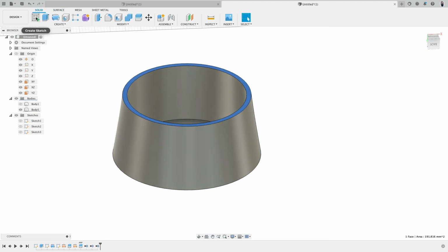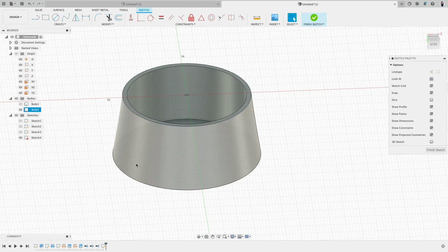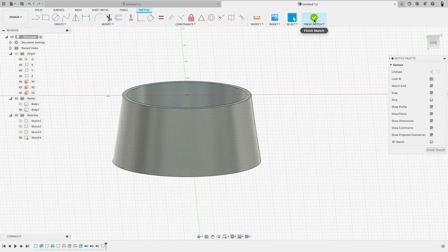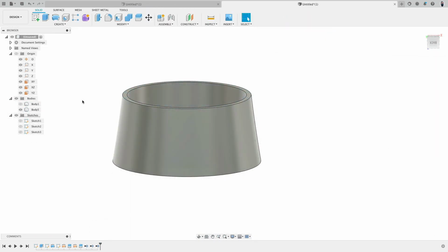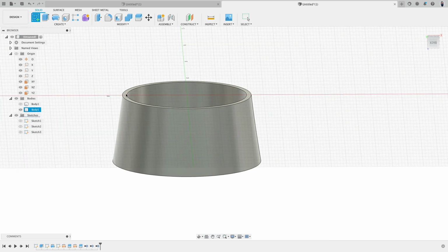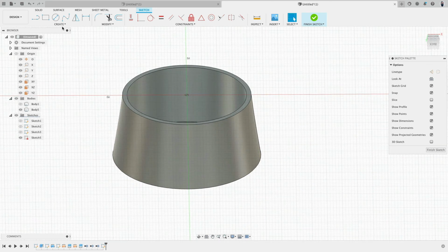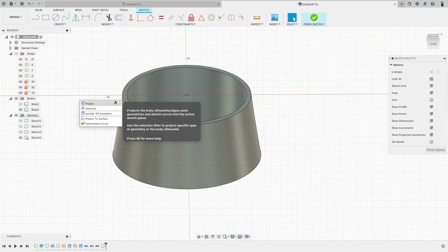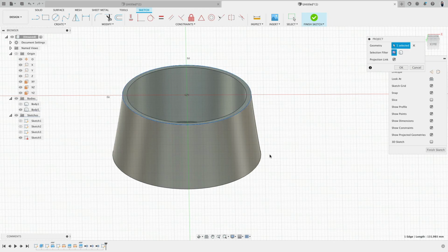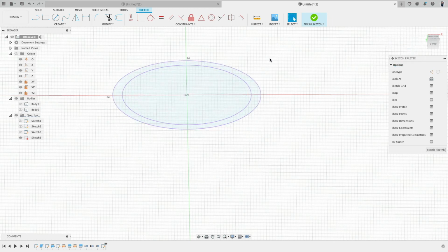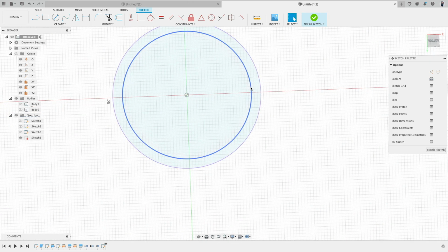Okay, solid mode, sketch right on this face I had selected. Or let me undo and delete this feature. Sketch. You see how I can select this planar thing. Very nice. Then P for project. This ring and this ring. Now I see the inner and the outer edge.